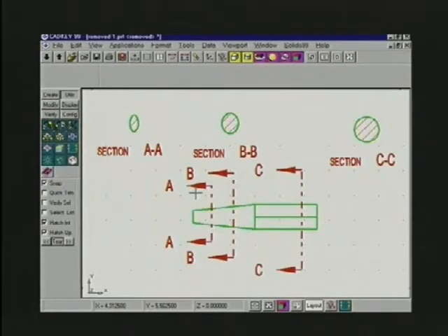And again, you would use removed sections when you have objects that are continuously changing in shape. And way down at the very end, this is very elliptical. A little farther along, where I cut section BB, it's not quite elliptical. Farther along yet, where I cut section CC, it's completely circular. Removed sections are another type of section that allows us to adequately describe the shape of an object.